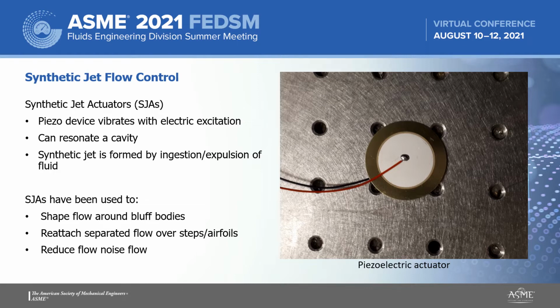The goal of this research would be to develop a control scheme that can be adopted to full-scale flight. This will likely require development of a closed-loop control scheme, which is being worked on by several groups, including the Turbulence Lab, and also further studies into the response of different flows to synthetic jet flow control. There's a need to characterize the kinds of structures which arise from synthetic jet excitation, which can change greatly with the control parameters, as we will see later.